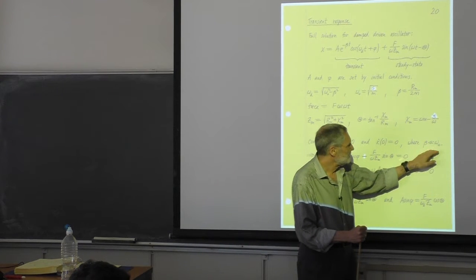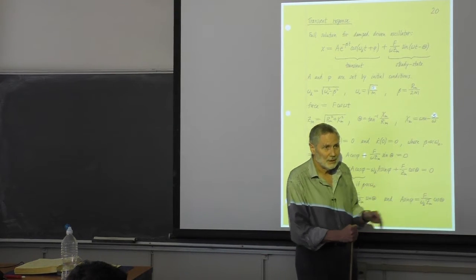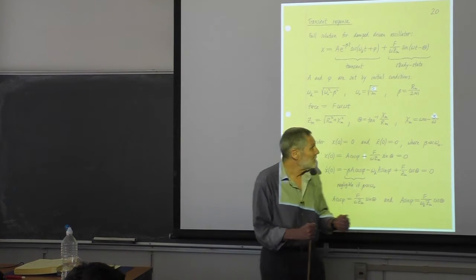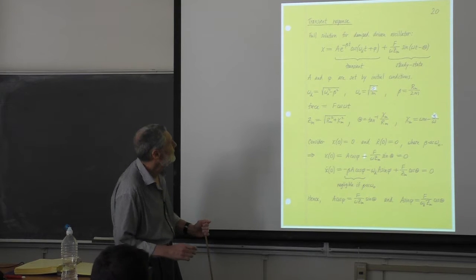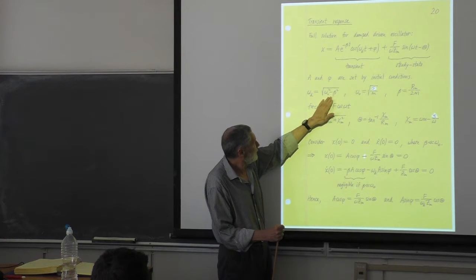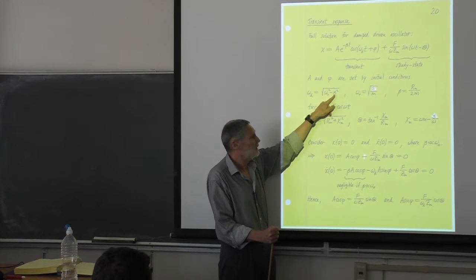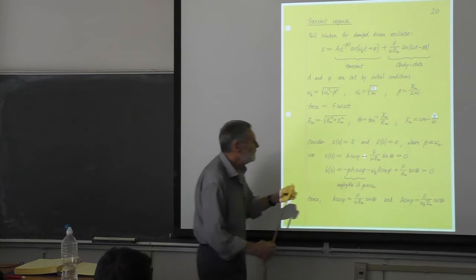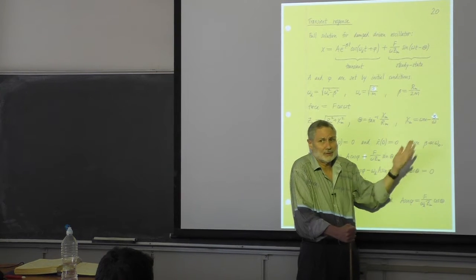They chose 10%. Now they actually have the damped frequency here, but because beta is small, the damped frequency and the natural frequency are going to be very close. They chose a beta of 10% of omega naught. Usually we don't think of that as small, but in this case it is small, because the effect of the dissipation enters in as the square. So with beta 10% of this, because of the squares, it's going to become a 1% effect. And then when you take the square root, it's about 0.5%. So it's small, right? When we make a statement like this, there's no universal meaning behind how small it has to be. In this case, 10% is typically very good.